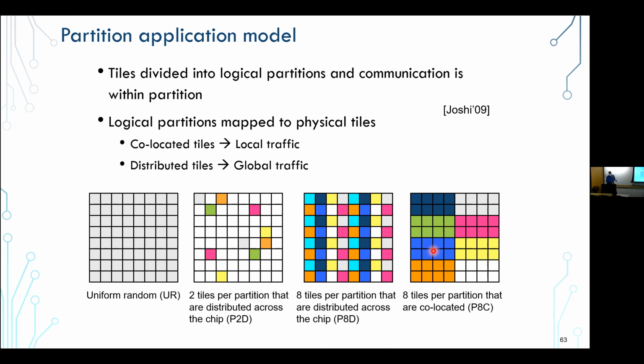Here, I would have to go from this partition to this, or in the worst case, from this partition to that partition. So all of these things matter, and you need to bring them in. One increases the channel cost from the core to the router. Another one increases the channel cost from router to router. And you need to be able to balance these out.